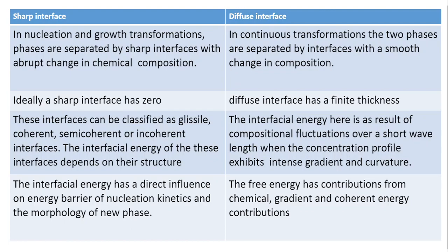The sharp interfaces can be classified as glissile or non-glissile. Among the non-glissile interfaces are coherent interfaces, semi-coherent interfaces, or incoherent interfaces. The interfacial energy of these depends on the structure.